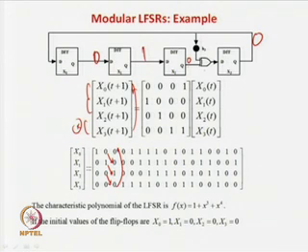So, it is 0 0, and now it is a 1 over here and a 0 over here. Now you can see the fourth vector. As we know, these two are direct controls over here. Now, this control from here to here will depend on the XOR of this value with this value. 0 XOR 1 is a 1. So, you get a 1 over here, and this one has a feedback over here. So, now you get 0 0 0, this one will be a 0 now, and this one will be a 1 now. So, this is your next vector.